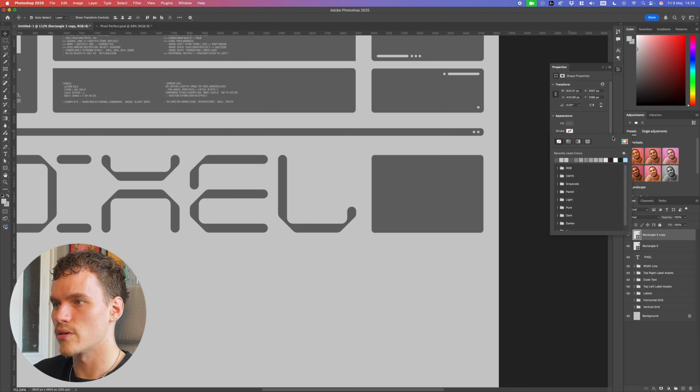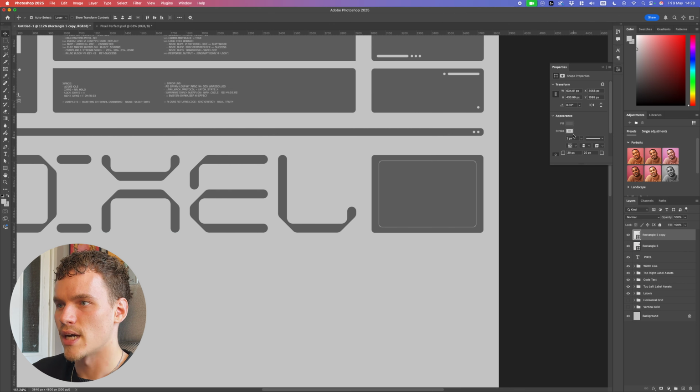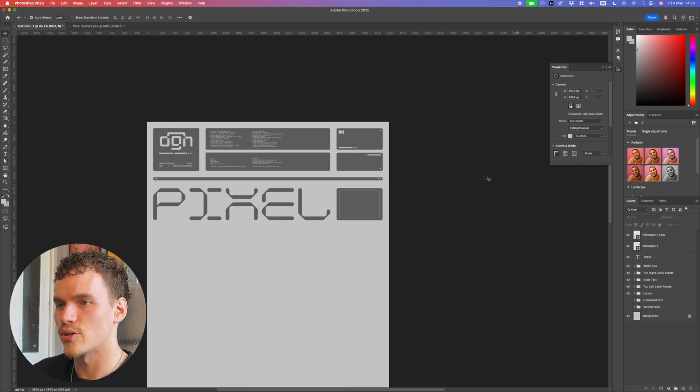And now we're going to use the stroke, set it to our background color, and remove our fill. Now this is just going to create this kind of inside line, just to accentuate whatever we have going inside. Now I'm just going to extend the width of this a little bit, make sure the placement's right. And now having a look at our pattern, all I've created here is this just shrinking size set of squares. It's kind of like a weird digital optical illusion.